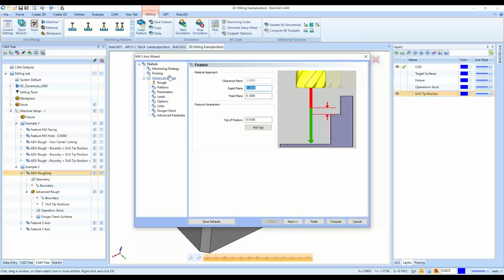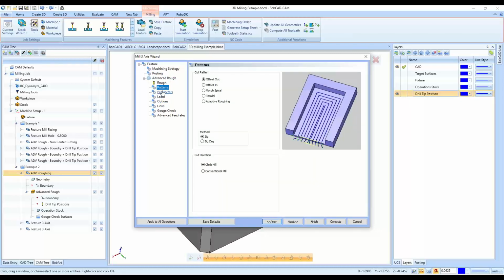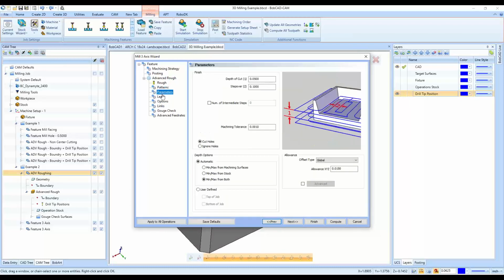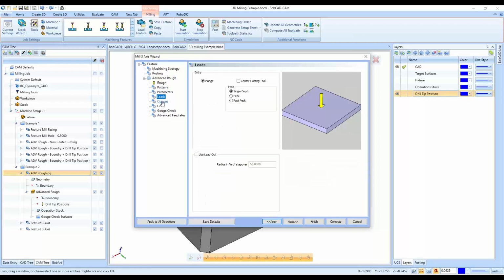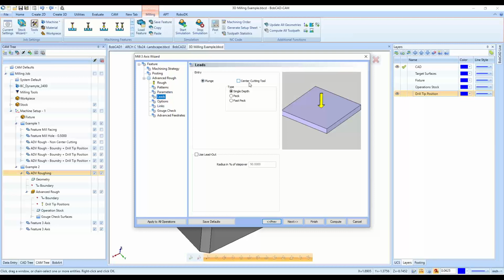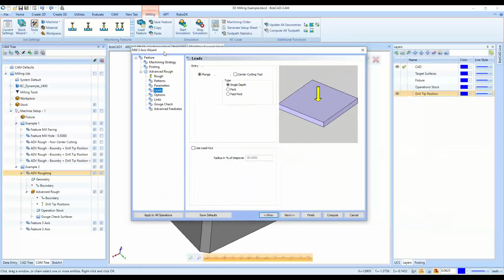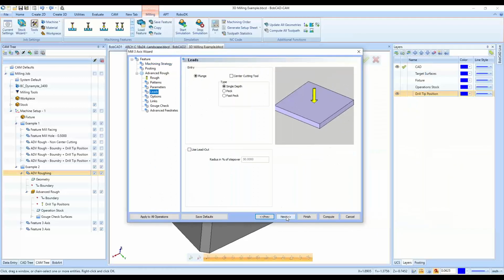We've gone through all of the settings here, setting the tool, setting the cut pattern, depth of cut, step over, and also that it's doing a side roughing routine in here. We've roughed all of this out already. It's going to start on the inside here, work its way in to the stock that hasn't been cut yet.